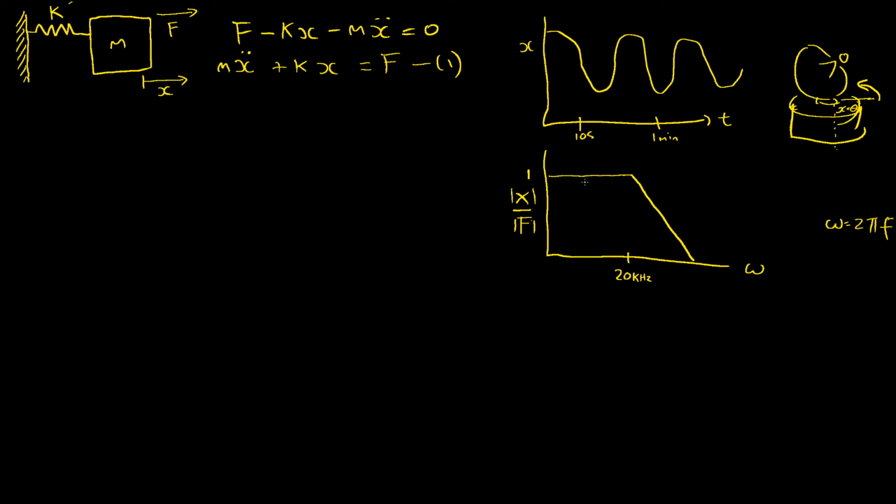And so what this is saying is this is a system with a gain of 1, so whatever you put in is just passed directly through to the output. But beyond 20 kilohertz, if I put in an input of 1, I'm getting less out. This ratio is going down and down and down and down. And so this would be heavily attenuating the output. If I put in down here a signal of say 1 volt, I might be getting out millivolts.